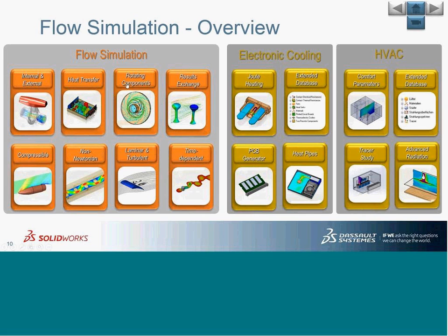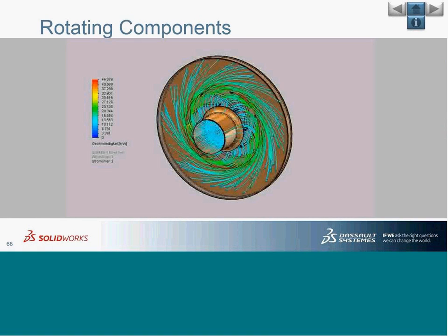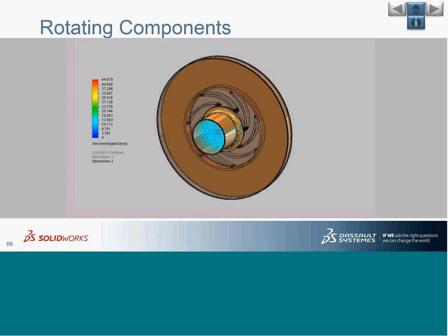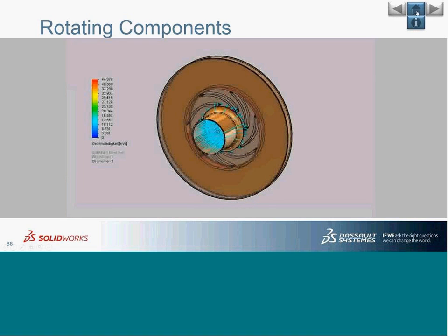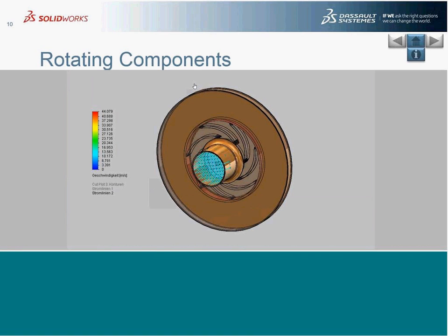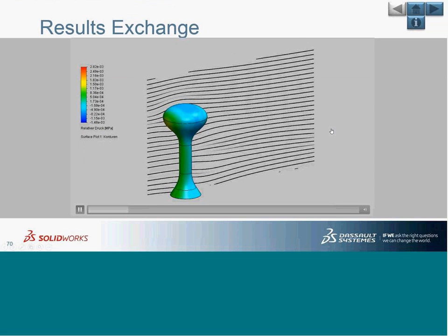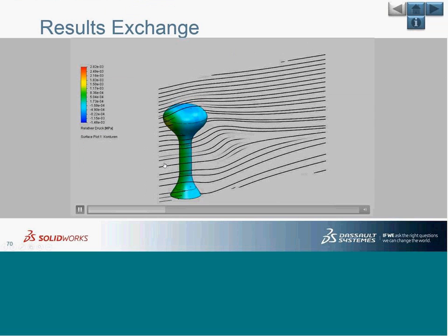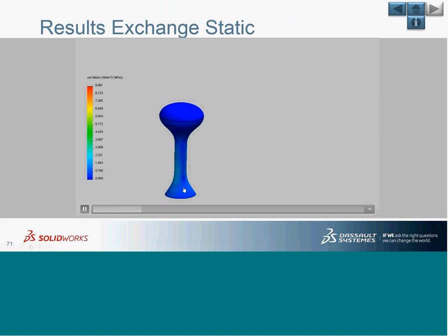It is not only the simulation of fluid, but you also have capabilities to transfer this fluid load to a shell load and do structural analysis on the components. Not only the fluid flow, but move them to structural and do the stress analysis. This transfer can be to our simulation software, and it is not only forces and pressures that are coming on the structure, but also the heat transfer happening because of the coefficient of convection. So we understand that aspect as well.